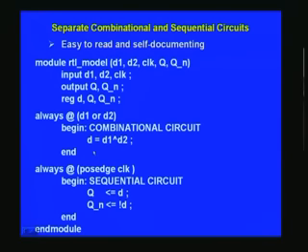So that is what we are doing here, and here you list all the inputs, which happen to be D1, D2 and clock, and you can put them like this or separate them out in different statements. So is the case with outputs, and you just list them, and we will see more details when we actually put all the code that we have learnt earlier in one file as a preparation for simulation later on.